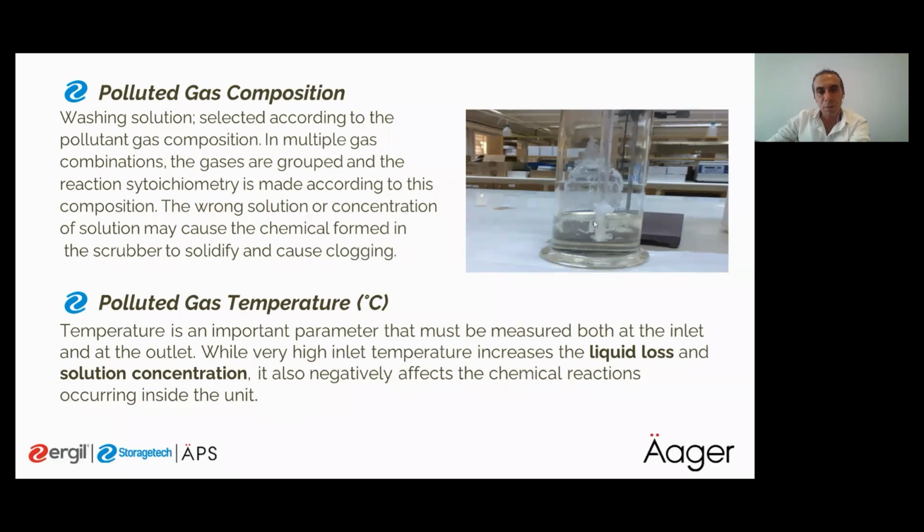And the gas temperature, the polluted gas temperature. Also, you asked whether the scrubber can use heat recovery. You have to reduce the temperature, because the wet scrubber's maximum working temperature is around 80 Celsius degrees, and the bioscrubbers can work around 28 to 30 Celsius degrees.